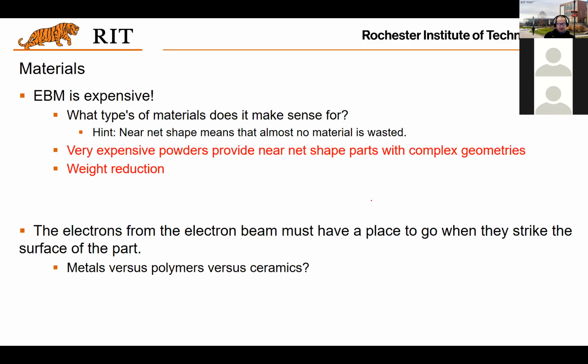Material: very expensive powder. And as I mentioned, there are quite limited choices for these powders. That decides that EBM is utilized for applications which require near net shape parts with complex geometry, or where weight reduction is critical. So in other words, some defense applications, aerospace, airplane parts, and so on.